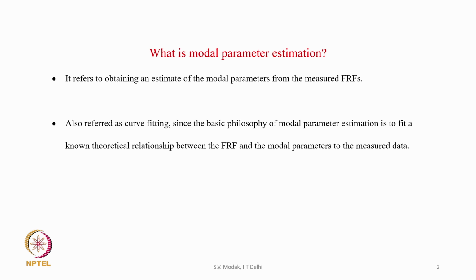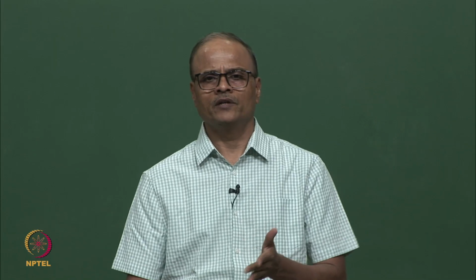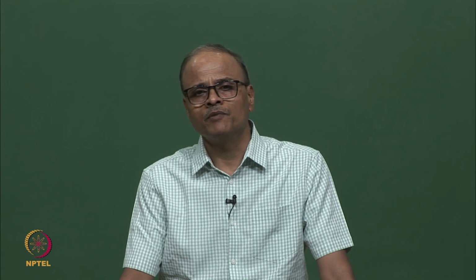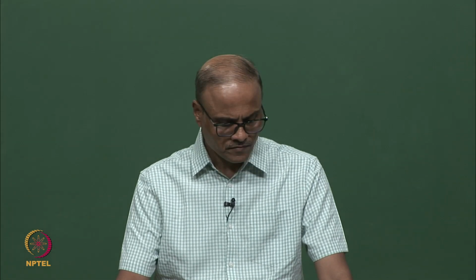This is because it essentially involves fitting a known theoretical relationship of the FRF and the model, or IRF and the model, to the measured FRF or IRF. That is why this process is also called curve fitting. We also discussed this in a previous lecture when we talked about the principle of experimental modal analysis.